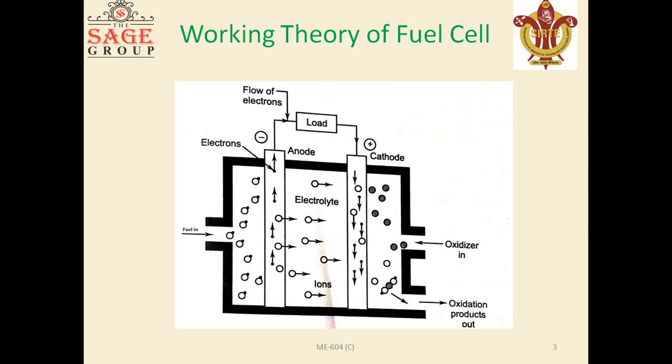The fuel cell is a device that keeps the fuel molecules from mixing with the oxidizer molecules, permitting, however, the transfer of electrons by a metallic path that may contain a load.